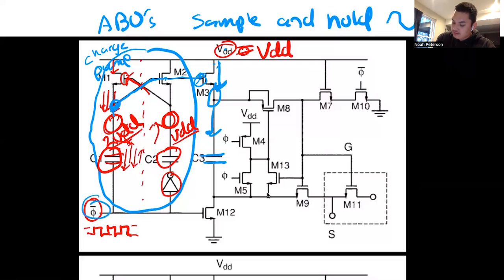And this C here is still oscillating, going back and forth. When there is a high voltage on the gate of an NMOS, it's going to turn this NMOS on and pull this whole component down to ground right here. This is going to be grounded. Since your charge pump is oscillating back and forth, it's going to allow this VDD to come into here and charge this capacitor up.